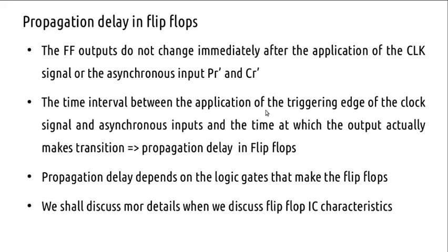That is the time interval between the application of the triggering edge, that is the rising edge in this case, of the clock signal and asynchronous inputs, if present, such as clear, and the time at which the output actually makes a transition. That is what we call propagation delay. Propagation delay depends on the logic gates. And we will see later that the logic gates are made up of transistors and diodes internally.